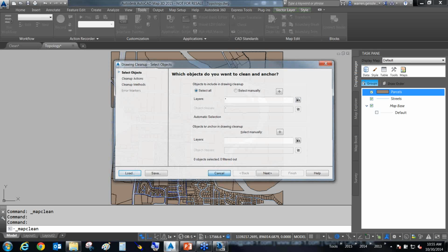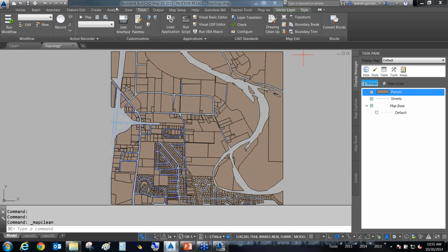If you've got Raster Design, which comes with the suites, you can use Raster Design to merge images together into one. You do have raster because you have some suites over there. However, even if you are using Raster Design and trying to merge images, you might run out of RAM. So you've got to be very careful with doing that.